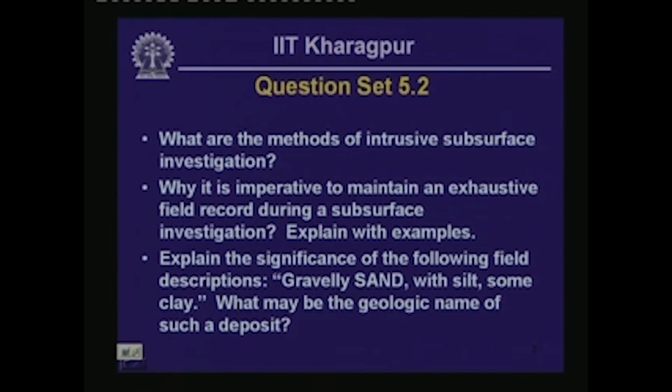and sampling. Now, the second question that I asked was why it is imperative to maintain an exhaustive field record during subsurface investigation, and I asked you to explain with examples. Now, the major problem that the designer faces is to get a clear picture of the layers that are there underground, and for this he or she needs to have an idea about the sequence of drilling, what kind of problems were encountered during drilling, and so on and so forth. Some of these issues I already have discussed in the previous lesson,